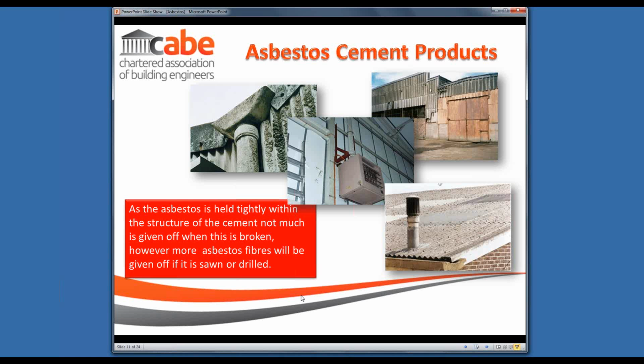Early in my career, I did deal with a very old theatre that had a large auditorium with asbestos ceiling tiles. They'd been identified as a potential risk. There was an annual inspection to make sure they were intact, but in the meantime they had been treated and sealed with a sealant so that no fibres could escape. The difficulty then comes if accidental damage occurs, or if somebody has to cut or drill into these materials, and that's when we can get issues with fibres being released and precautions have to be taken.